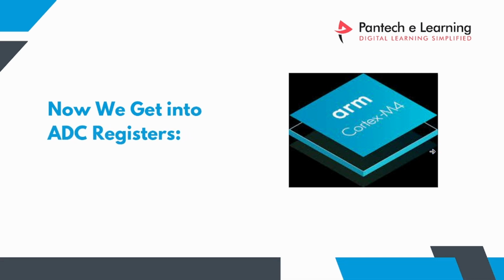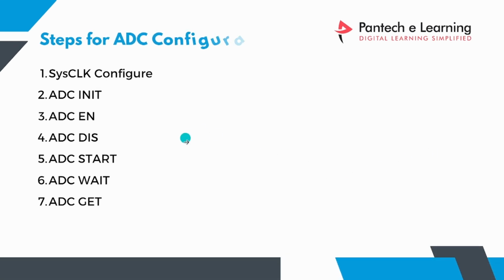So we are going to see the registers. Before that, we will see the steps for configuring the ADC. These are the functions we are going to create. System clock: we are going to configure the PCLK2 as 8 megahertz. We are not going to use the PLL in the system clock. We are going to directly use the HSE main crystal for the peripheral clock source. Then we are going to create the ADC unit function, for ADC enable and disable, and for starting the conversion. We are also going to create a wait function, and we will get the data.